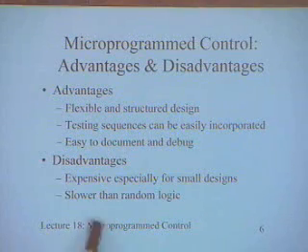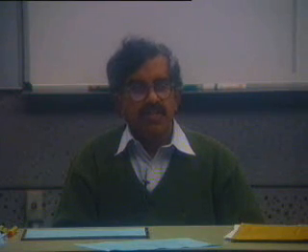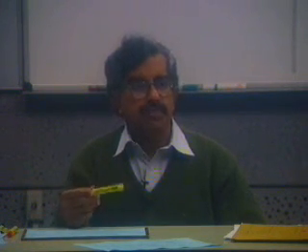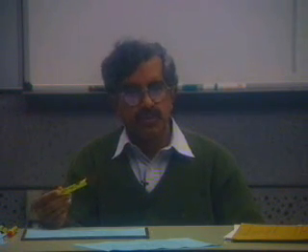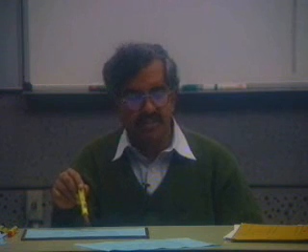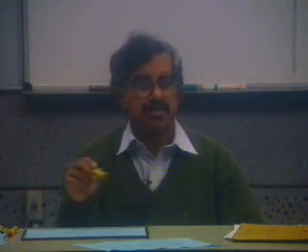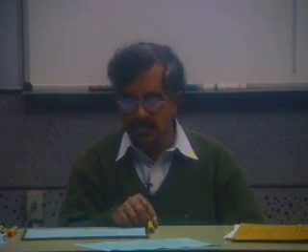So microprogramming is still used when you want a flexible and structured design. Another reason it is used is when you are doing prototyping. Many times people use microprogramming because you are in the development stage. A lot of changes are going to come in the control, in the protocol, in the interfaces. So you go ahead and do a microprogram design. At the end, when everything is frozen, once you are very satisfied with the design and it's going to go into production, you reduce the cost and the size and increase the performance speed by translating such a microprogram design into a random logic design. So sometimes a two-stage process is also followed.